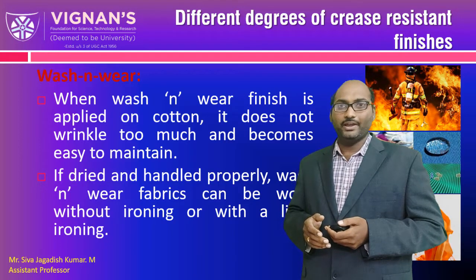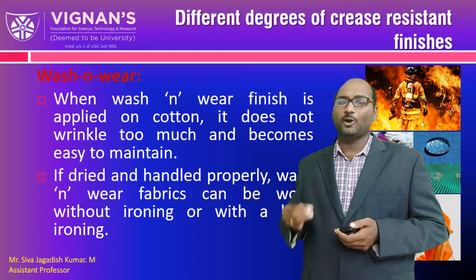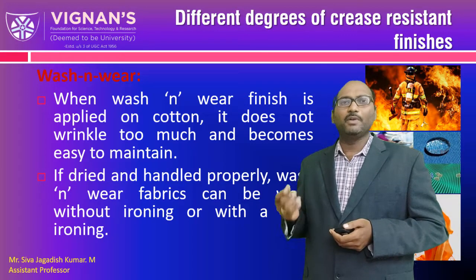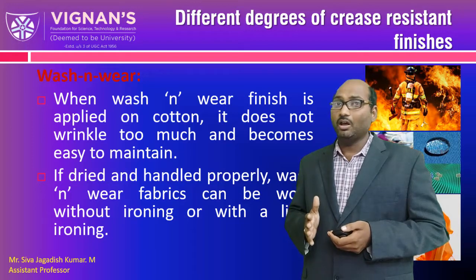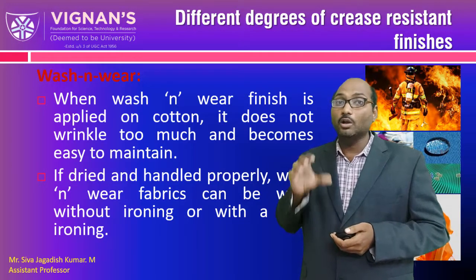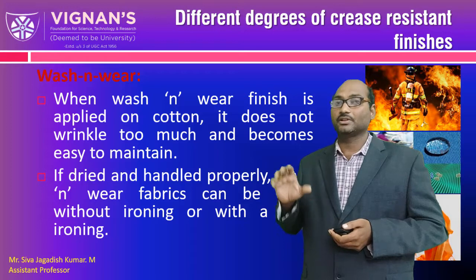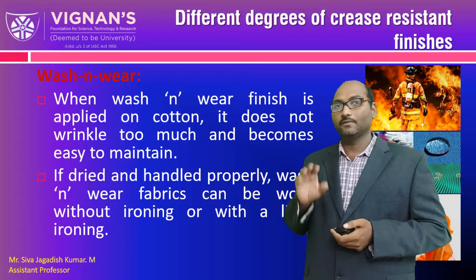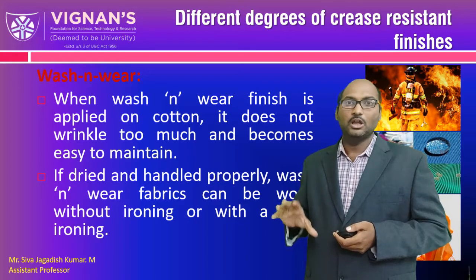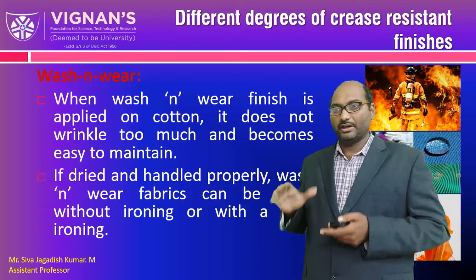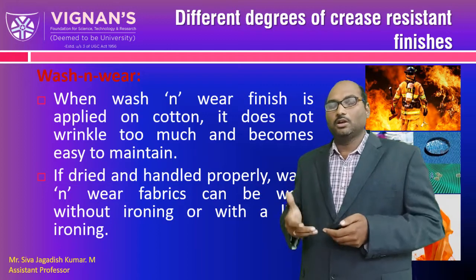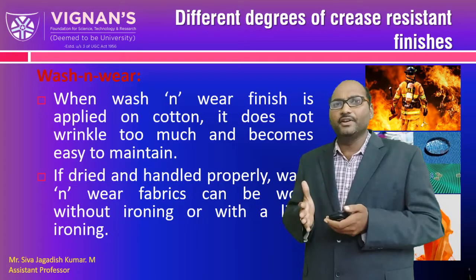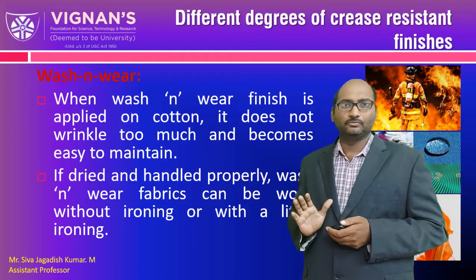Okay. So again, these are synonyms, depending upon how much resin we are giving. Some brands will name it something else. But the core concept of these wrinkle resistant finishes is the same: the resin reacts with the free OH groups of the cellulose and restricts the bonds from forming in between, so that the fabric remains flat in its nature. Okay, that is common.